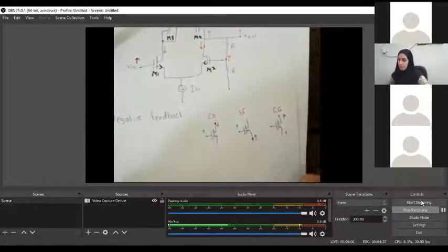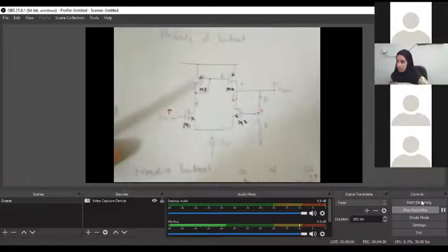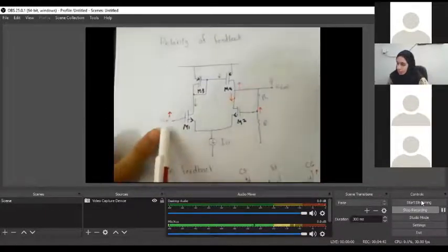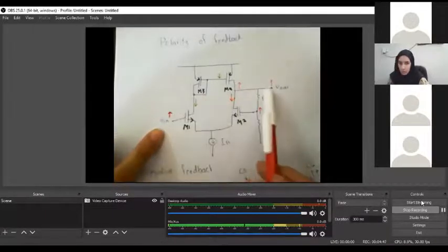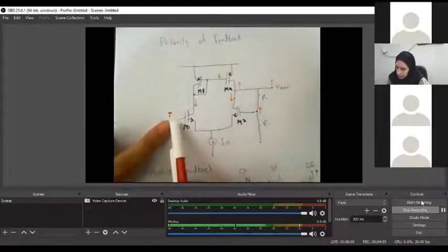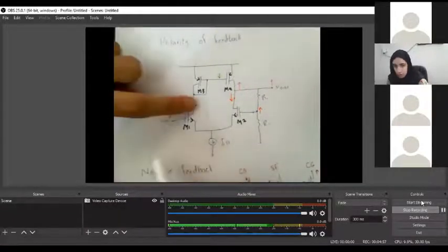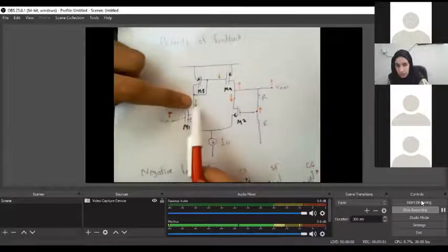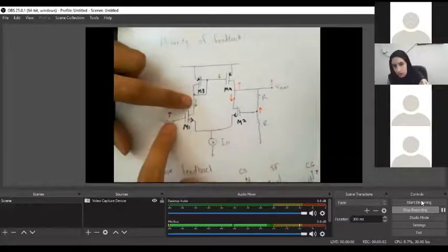Okay, now we come back here. If I start from the input, go through until the output, and then go back through the feedback to see what changes this brings. If I am increasing the gate and looking at this point here, it's a common source case, because the input is applied at the gate and I am checking at the drain point.